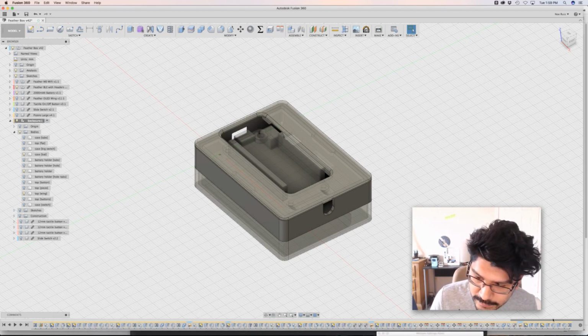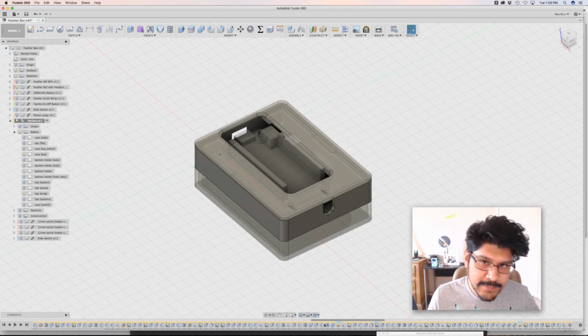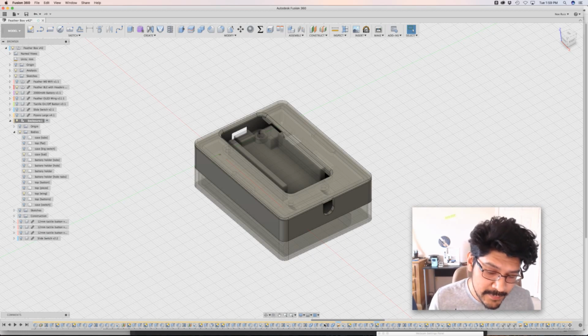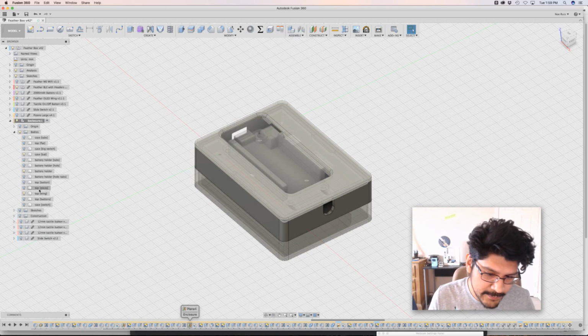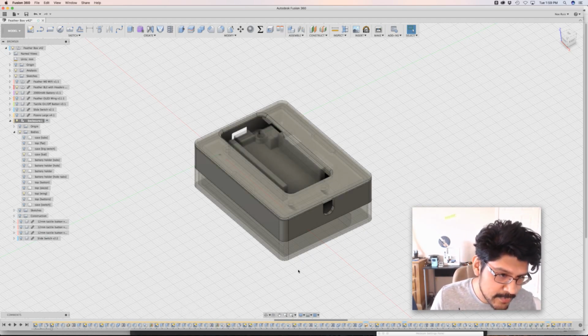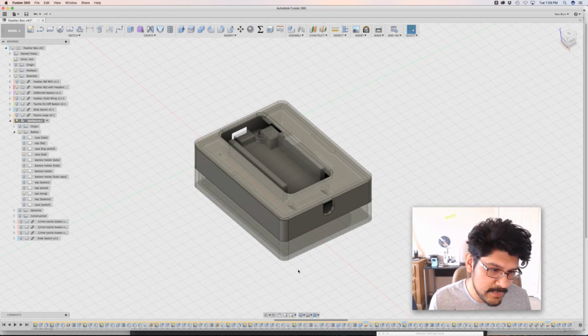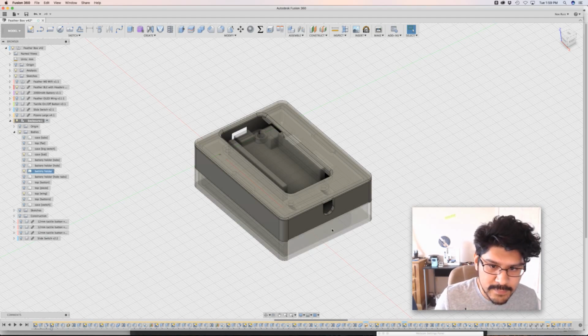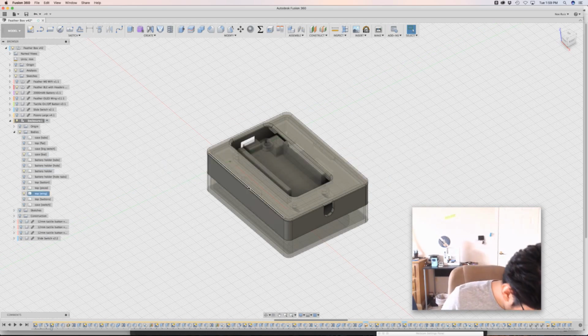Another thing to do is to group certain segments, but in order to do that I have to rework the order of operations so that they make sense, so that I can group them. Maybe I would group different toppers into different segments here, or put them in components, because when you use components they tend to encapsulate their own features in their own timeline. So there's still things to do there. Let's see, what else do I have here?